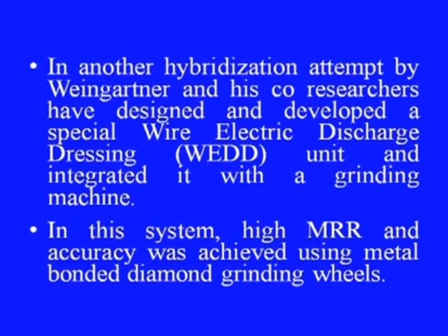Wegener and his co-researchers have designed and developed a special wire electric discharge dressing WEDD unit and integrated it with a grinding machine. In this system, which is also a hybrid system, high material removal rate and higher accuracy were achieved using metal bonded diamond grinding wheels.